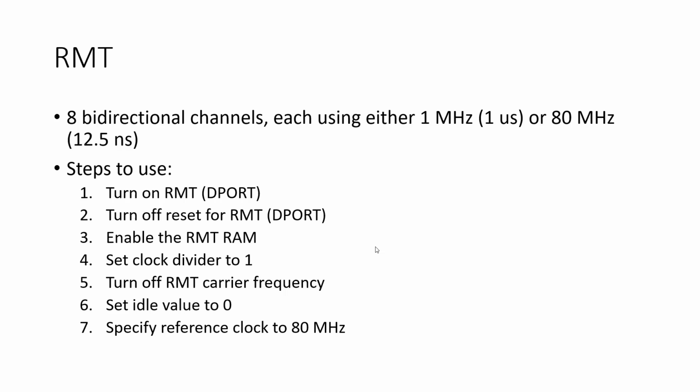Now, you might say, is there really 200 peripherals on the ESP32? Yeah, there's a lot. I mean, not 200, because some peripherals have multiple signals associated with them, but there's a lot. But they're all powered off by default. So you've got to turn them on. But then that's not enough. Even after you turn them on, they're in a reset state. That's ridiculous. If you turn them on, you obviously want to put them out of reset, right? But you have to turn them on and then take them out of reset.